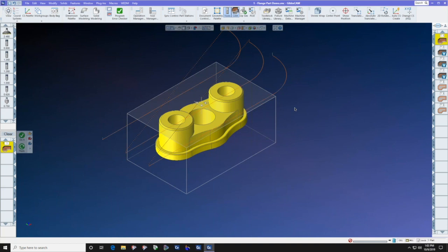So the steps of machining from a solid, we're going to go through step by step in this presentation. We have several solids that we're going to work with, and we're talking about 2.5D solids rather than three-dimensional solids. Three-dimensional solids would require us to use a ball end mill or maybe a barrel type end mill to do surfacing on surfaces that are not planar to the normal axis of the machine.